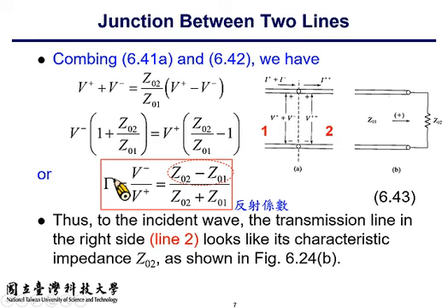So again, you take the first term on the numerator is what? Is the characteristic impedance that you are looking into from your propagation direction. The characteristic impedance on the other side, that is Z sub 02 in this case, minus the characteristic impedance from the incident side, that is Z sub 01, over Z sub 02 plus Z sub 01. Okay? I bet that you should have already memorized the definition of the reflection coefficient.